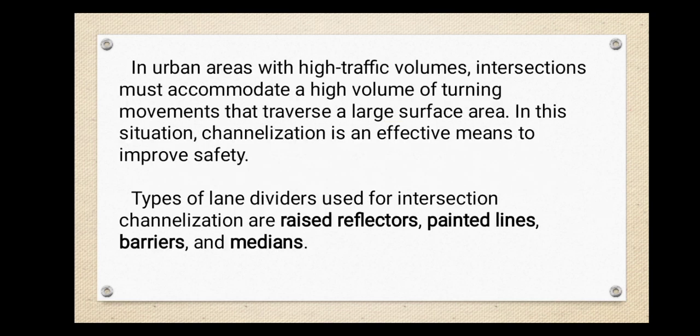So, in urban areas with high traffic volumes, intersections must accommodate a high volume of turning movements that traverse a large surface area. In this situation, channelization is an effective means to improve safety. So right turn only lanes have become recognized as a simple means to separate through traffic from slow turning traffic. For left turning traffic, however, several options are available, including left turn storage lanes and raised dividers to guide traffic